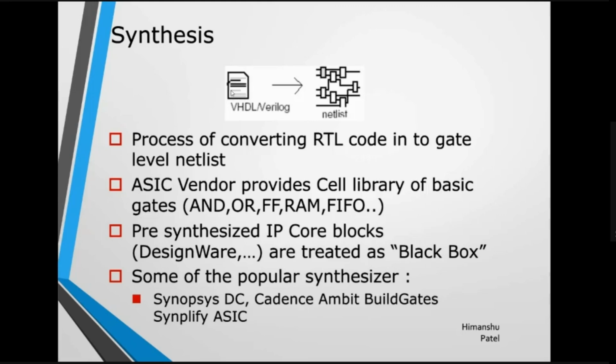A few people will say, do not go inside my IP, just use it as a black box and stitch it. Black box means you will have only the input and output ports of that particular module. Let's say it's a full adder, a 16-bit full adder. Only inputs and outputs are present. You cannot access the functionality logic and the behavior of that particular IP. So you tell the tool, okay, this is a black box module.